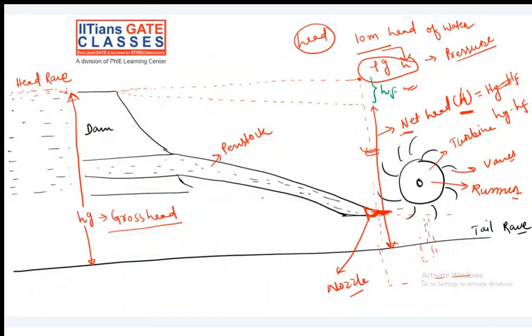And one thing I have told you, reaction turbine. In a reaction turbine, we have pressure energy, and this pressure energy gets converted into kinetic energy, and then it hits these vanes. But in the other case, all the pressure energy is not converted into kinetic energy, only partially, so I am left with some pressure energy and kinetic energy as well.